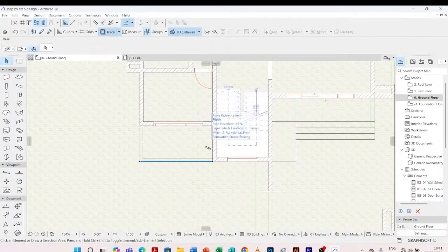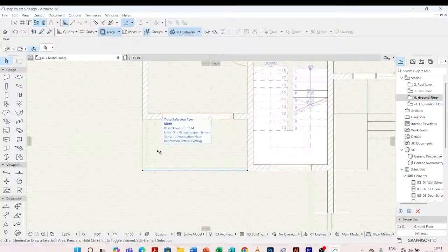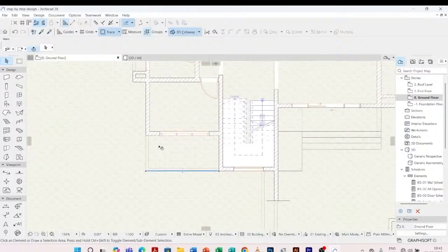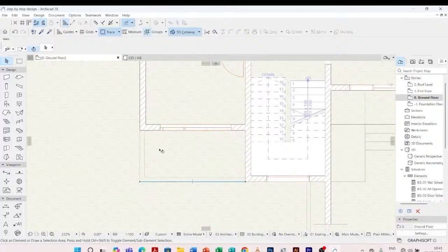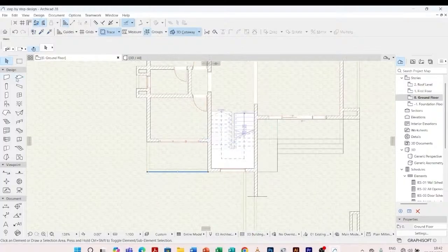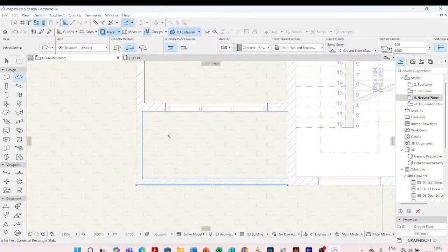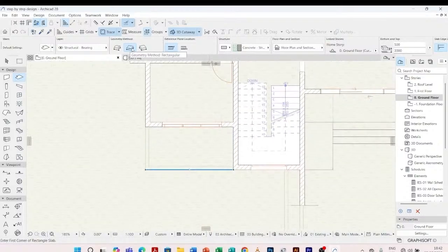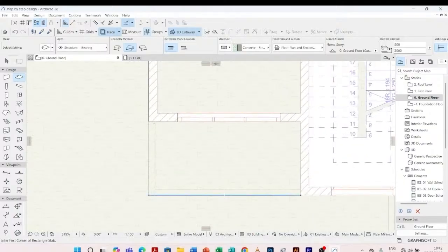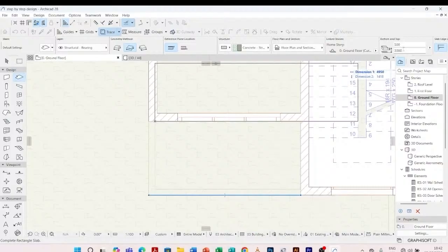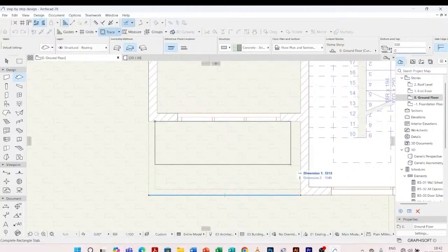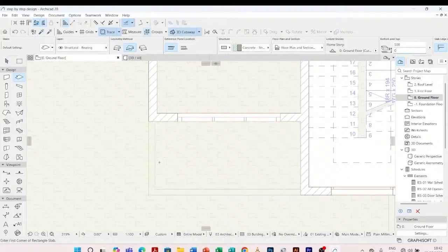Click this, our slabs here to create the soil. You can use a mesh tool, you can use slabs, you can use morphs, but we are going to use the slab tool to create the soil in our planters. So I'll come to the slab tool, I click on it, I'm going to draw a slab in here. So I'm going to go with the geometrical method, which is the rectangular method. I'll draw my slab here. On the ground floor it is offset at 3 meters. This will be 0. Then the thickness we shall adjust. I have a slab there.